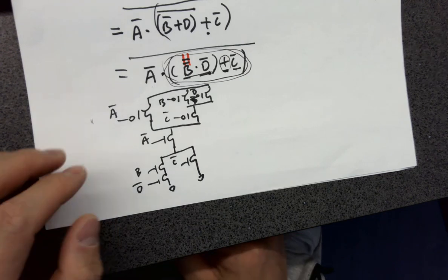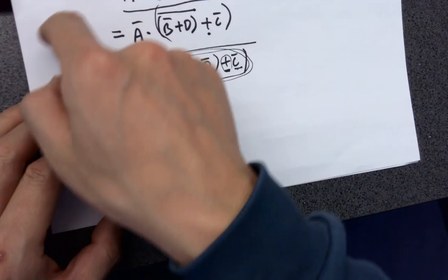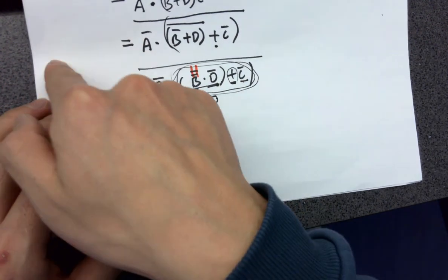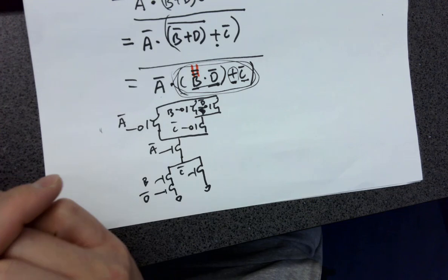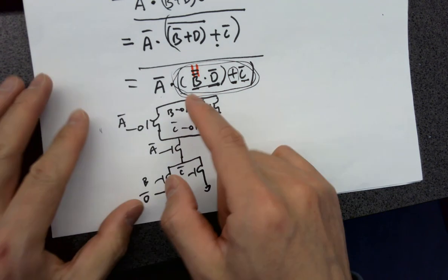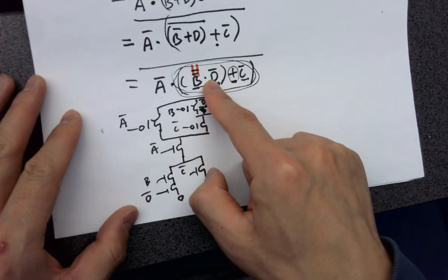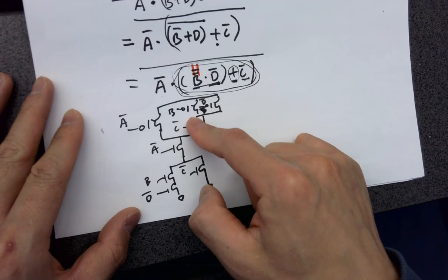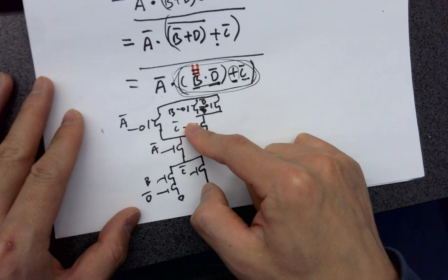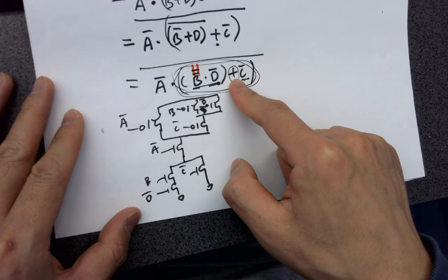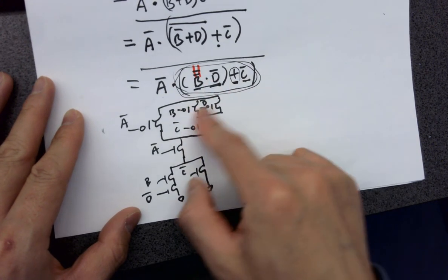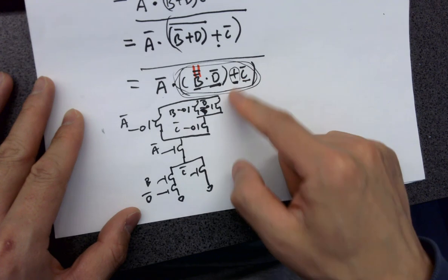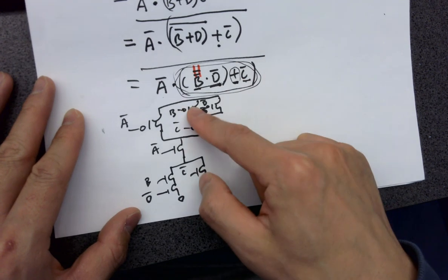Just keep in mind, it's actually really simple. You probably want to write a note somewhere when you are working on this kind of problems. Okay? So if you see an AND logic, you have series PMOSes. OR logic, parallel PMOSes. AND logic, parallel PMOSes, OR logic, series PMOSes.